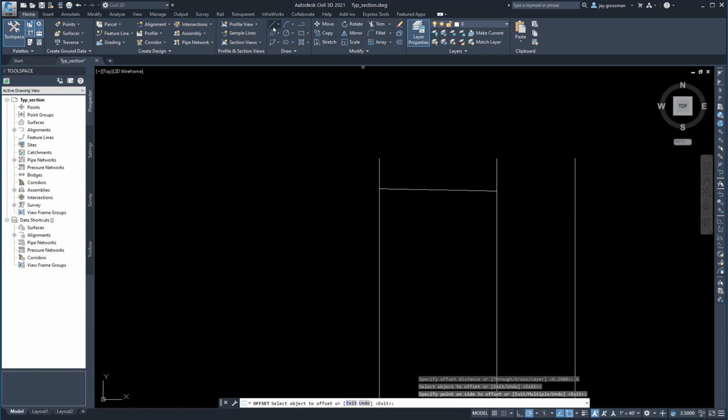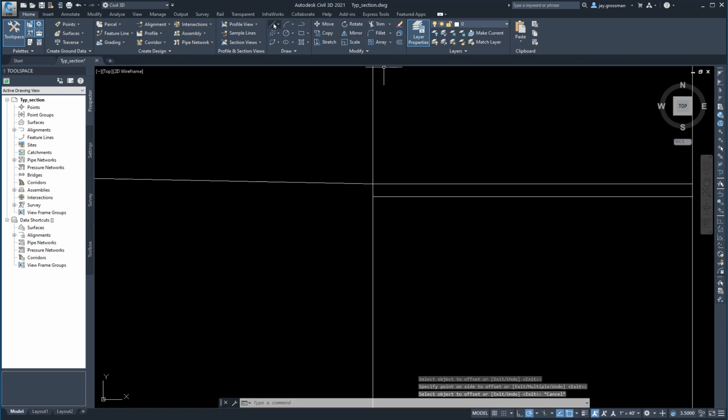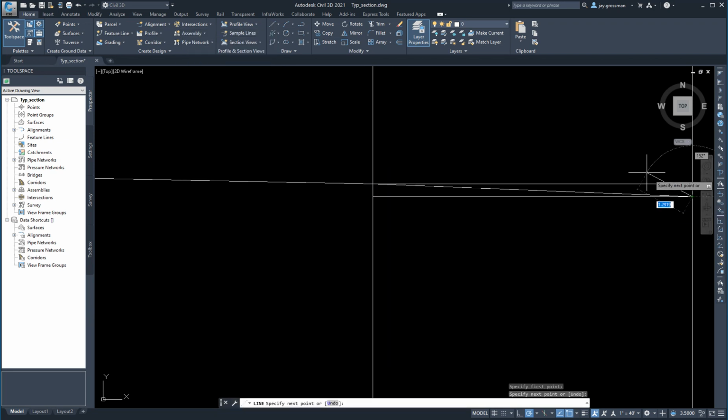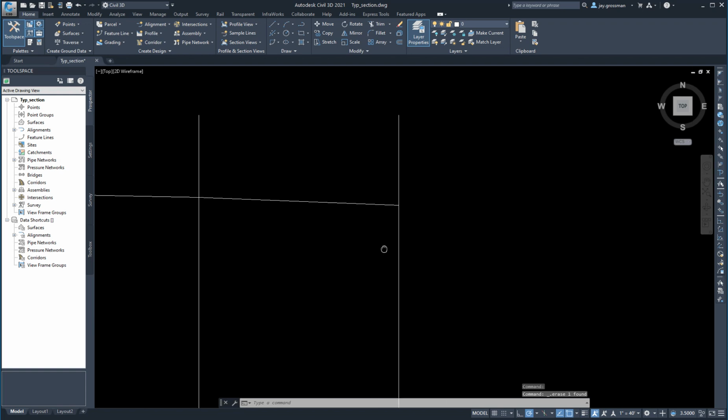All right, so I'm going to do the same trick I did before. I'm going to start here. I'm going to snap to the end of that line using the endpoint snap. Perpendicular, cancel. I'm going to offset this now. I'm going to offset 0.32, because that's the drop. It's how much it'll drop over 8 feet at 4%. All right, hit escape to get out of the command. Come back here, draw a line, create line, snap to that point, snap to that point, cancel out of the command. Delete these guys. Don't need those anymore. All right, there we go.